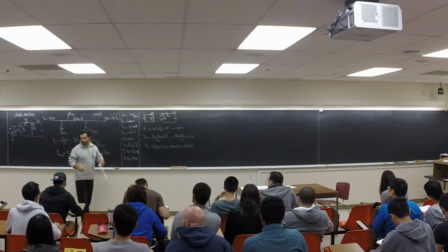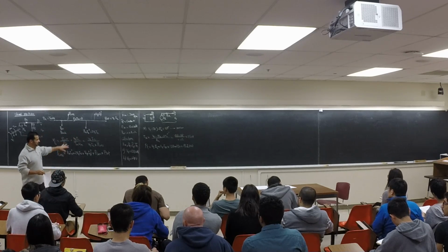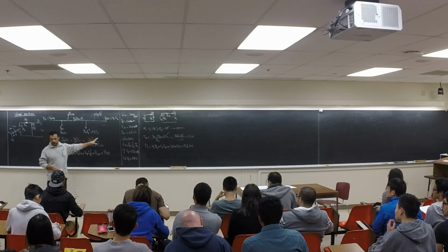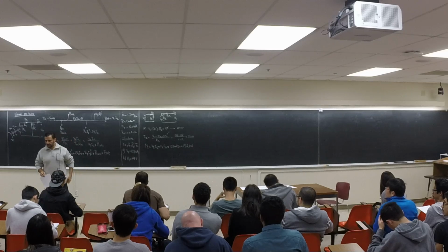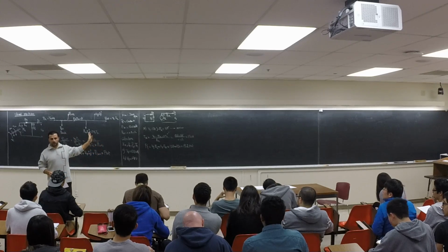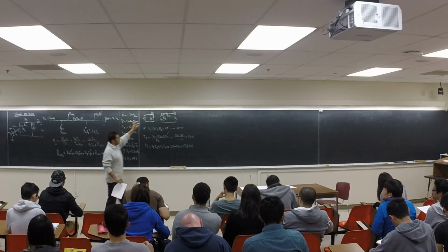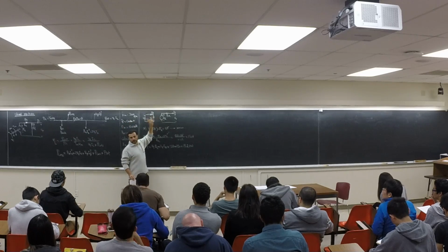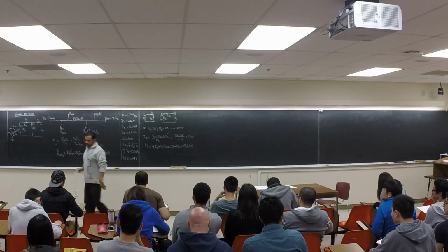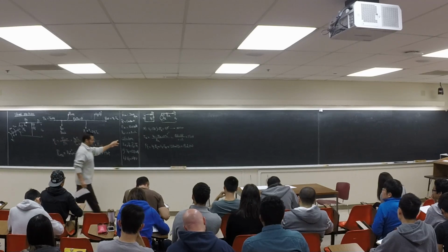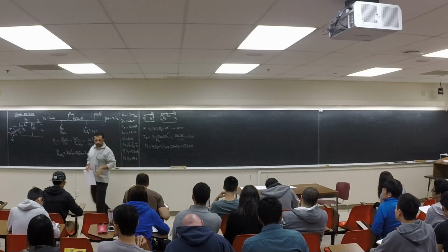Sorry, I missed it. Can you tell me why ED was zero? Because it didn't say anything. If it didn't give us any information about the brushes, just ignore it. Unless you tell us, for example, the drop voltage of the brushes is 1 volt, so there's 1 volt here, 1 volt here, and you have 2 volts, 2 VB here. But it didn't say anything, so I put zero. The full complete equation is this, but because it didn't say anything, I ignored this part.